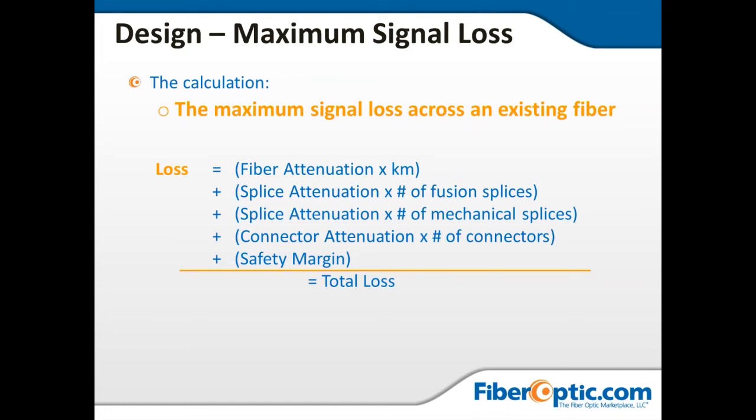So the calculation of your loss budget has to be done at operational wavelengths. We need to know what the loss is and how it fits into the range, or the sensitivity, between an amplifier and receiver through our cable plant to determine how well the system will work. But as I said, since the fiber is wavelength sensitive, we would calculate that, because what would work at 1310 might barely work at 1550 and not work at all at 1625, where losses are lower but become extremely more sensitive. So here's the little math formula if we build a physical plant.